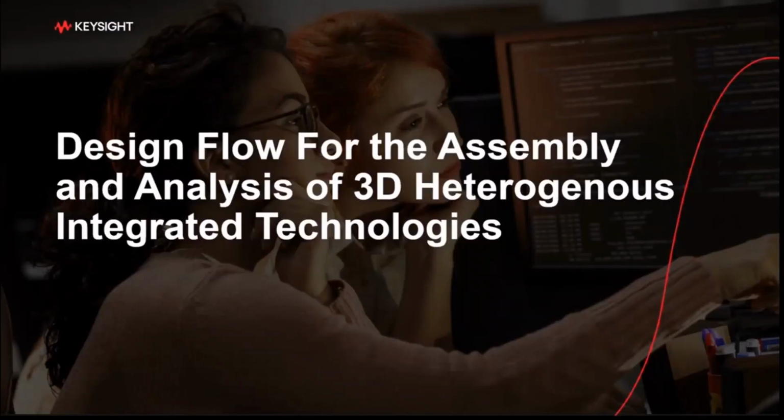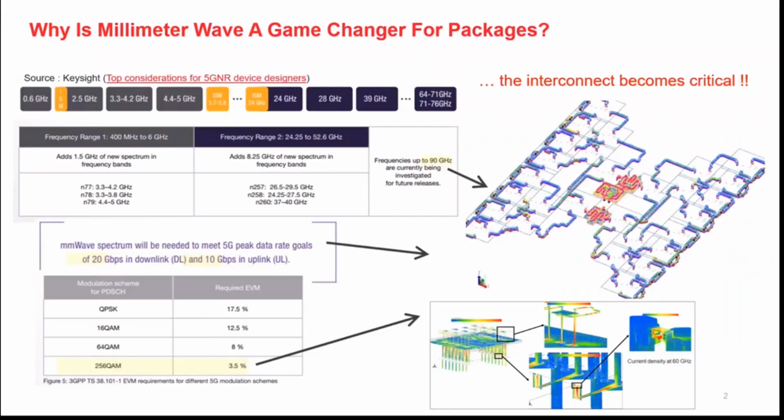Thank you, Ed. I'm going to dive a little bit deeper into the flow and how this is built using ADS. Everything is going higher in frequency. The bandwidths are getting larger. All this is driving higher spectral components into the designs that people have to account for and handle. One of the big problems with these higher frequencies is parasitics and interconnect, for example, that people used to be able to ignore can no longer be ignored. These now become very important parameters to the design and have to be accounted for.